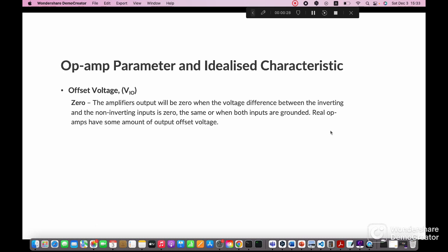However, real operational amplifiers, such as the commonly available UA741, for example, do not have infinite gain over bandwidth, but have a typical open loop gain, which is defined as the amplifier's output amplification without any external feedback signal connected to it. For a typical operational amplifier, this open loop gain can be as high as 100 dB at DC. Generally, an op-amp's gain decreases linearly as frequency increases, down to unity gain or 1 at about 1 MHz. This effect is shown in the following open loop gain response curve.